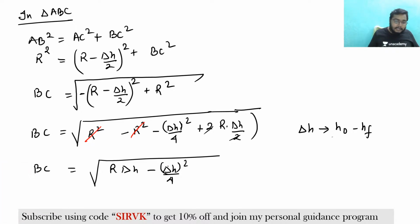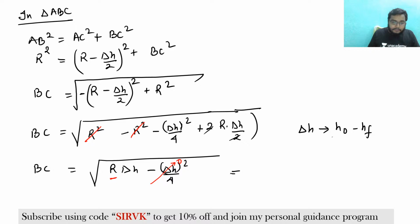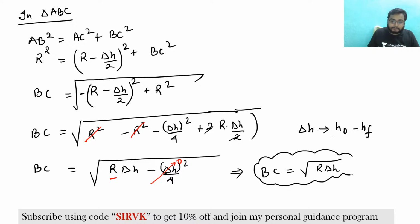So at this point we are neglecting this to be 0 for the sake of calculation. Again I am saying, to make the calculations easy, we are neglecting this, because this is a very much smaller quantity when compared with the radius of the roll. Fine. So what we are getting from here is BC equal to root over R delta H. And this is the length of deformation.